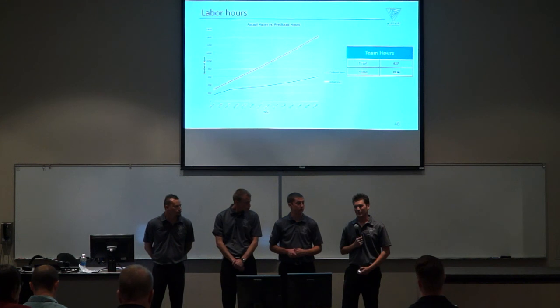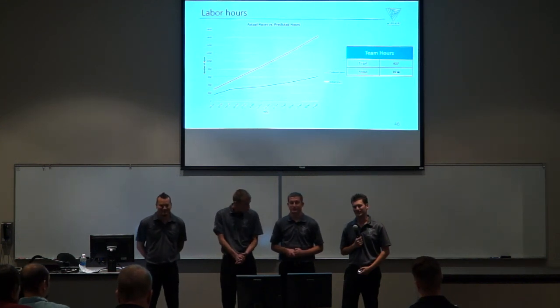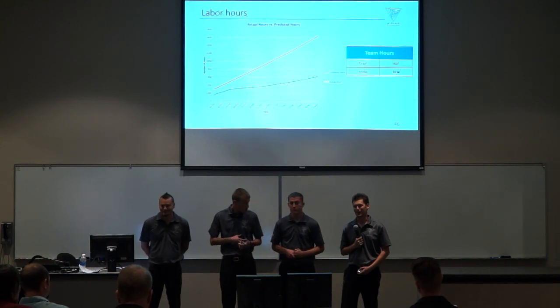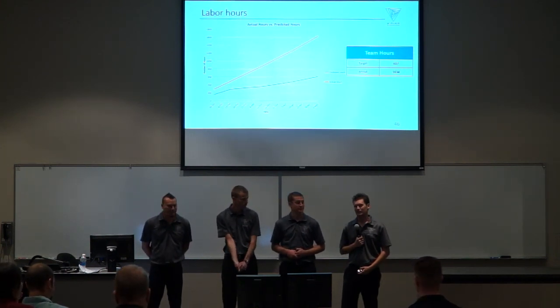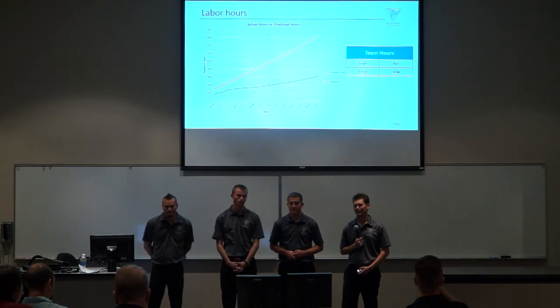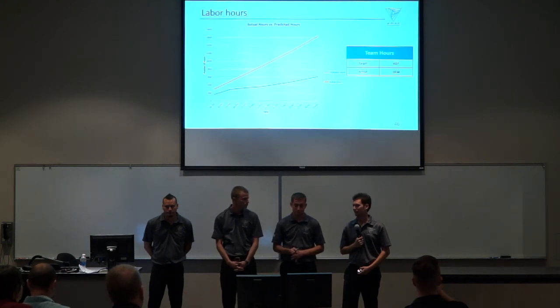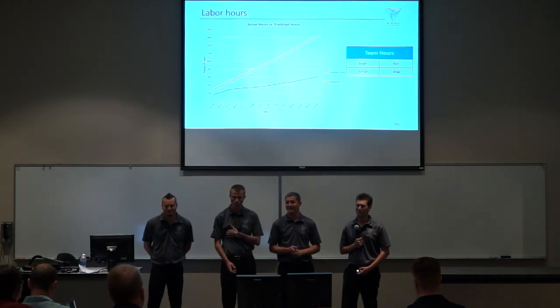Oh, we're proud of our testing dates, because I pulled the valve cover off yesterday and I have a problem on the number 4 intake rocker. Do you attribute that to running unloaded? Yes. That was from the beginning. We looked into finding a hydraulic pump and tying the lines together and putting a load on it. Didn't have money for that either. They wouldn't give one to me.